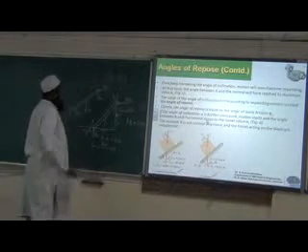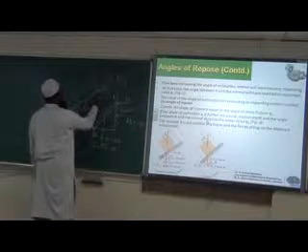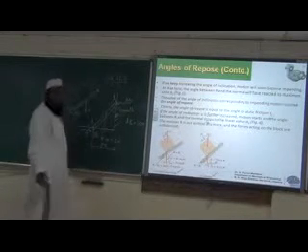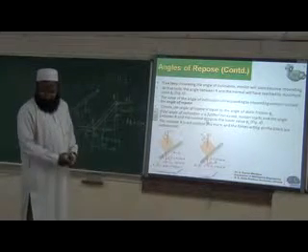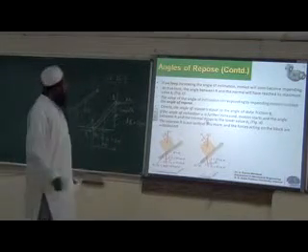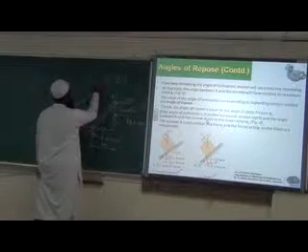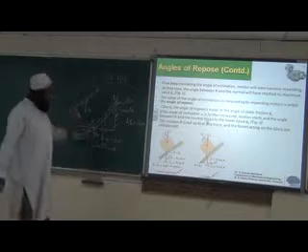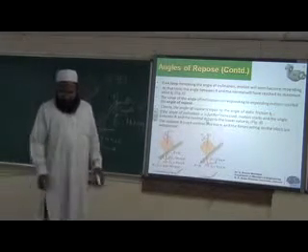First we draw the free body diagram. So no frictional force, and only a normal reaction, as it is a smooth wall. If it is a smooth wall, the friction can be neglected. Only for a rough wall will we consider it.